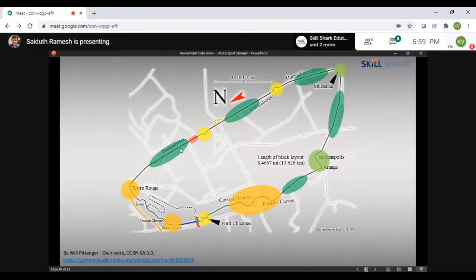Okay. Next, heavy braking zones. See the heavy braking zones that are popping up over here at the back straight. You also have a heavy braking zone into this section. And the final part for tuning the differential, you need to look at these low traction zones. Low traction, that's why I've put a slippery sign. You're accelerating out of a slow corner, you spin the wheels too much at the back, your car spins out. So something else for you to look at. Low traction here, here, and here.